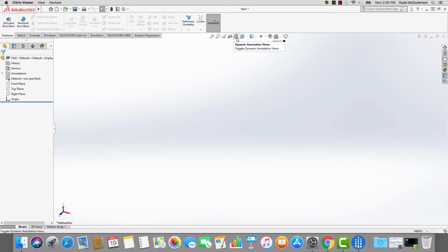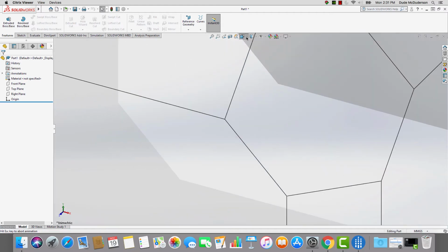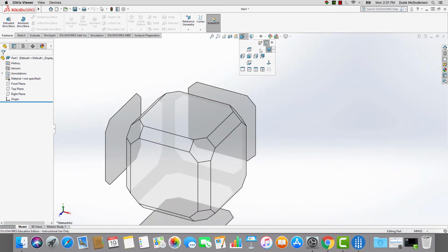You can actually add your own, you can annotate the views, so that words or text pop up when you create a view, and you can create your own view specific to a side that you want to look at. The view orientation, this is something we'll actually probably use quite a bit. This allows us to transfer between front, top, side, or an orthographic projection. If you click the little arrow next to this icon, it will open up the view cube, with this very handy little navigation window that allows you to look at things.